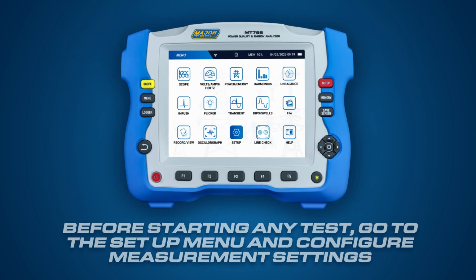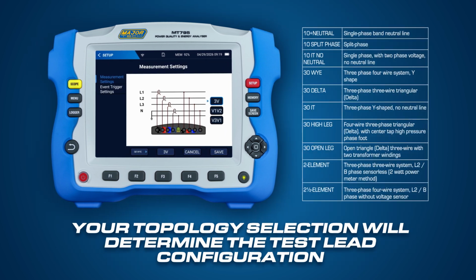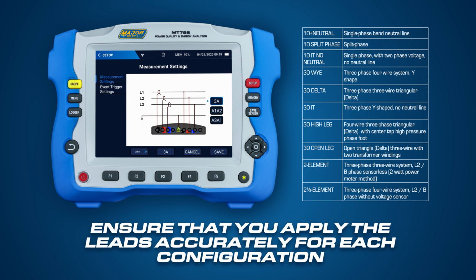Before starting any test, go to the Setup menu and configure the measurement settings. Your topology selection will determine the test lead configuration, which the meter will display on screen for reference. Ensure that you apply the leads accurately for each configuration.